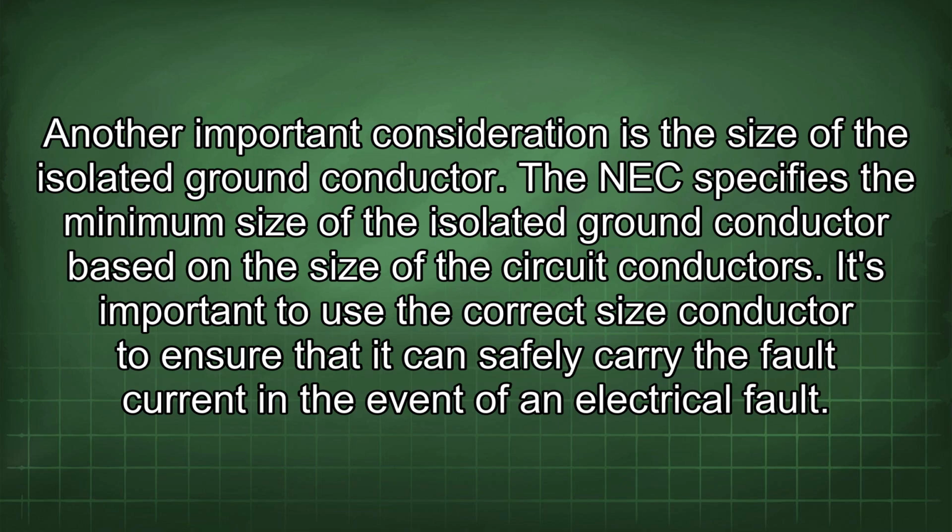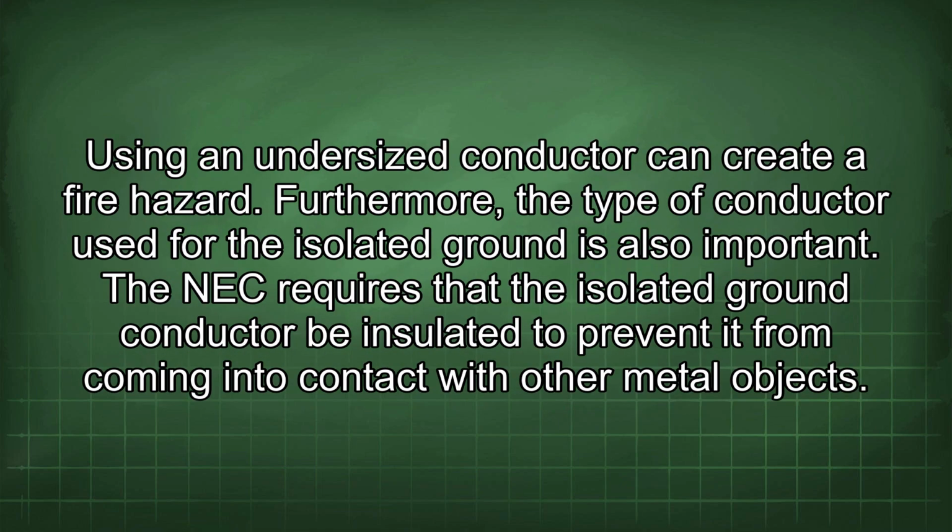The NEC specifies the minimum size of the isolated ground conductor based on the size of the circuit conductors. It's important to use the correct size conductor to ensure that it can safely carry the fault current in the event of an electrical fault. Using an undersized conductor can create a fire hazard.